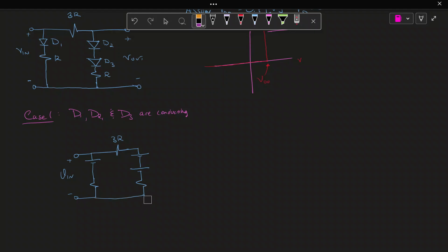You might be wondering why I put the battery in this way. If we remember from physics for EMF, they always had the longer leg as positive, and we want these diodes to have a voltage drop. So going from plus to minus, you have a voltage drop of 0.7 volts.